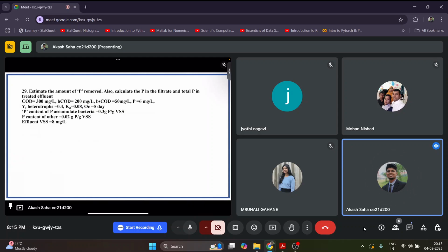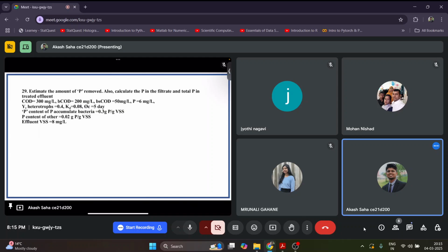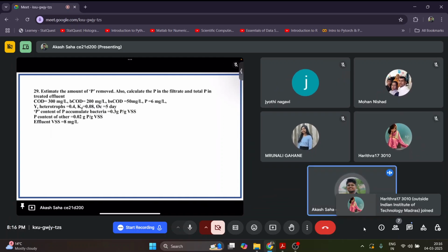BCOD, what is BCOD? It is biological COD. And what is BSCOD? Out of the biological COD, how much is biologically soluble COD? We have soluble and particulate COD. So BSCOD is 50 milligram per liter. Out of the 200 milligram per liter of BCOD, 50 milligram per liter is soluble. Then phosphorus concentration is initially 6 milligram per liter.